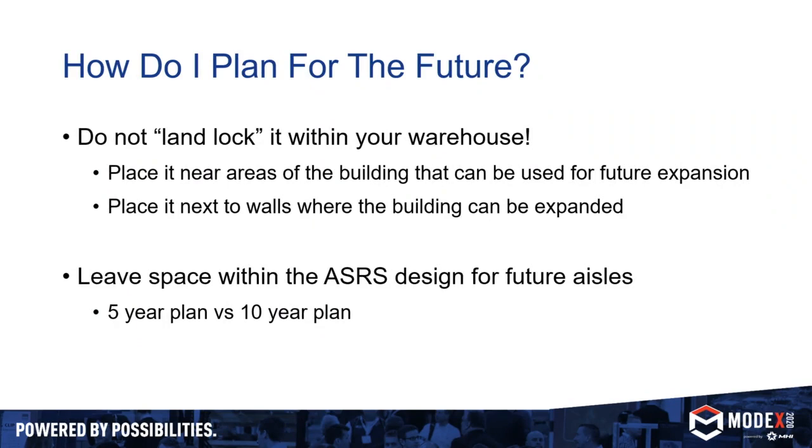And that goes into the next slide. How do I plan for the future? You don't want to put this ASRS somewhere where it's in a room, or off to the side, or somewhere that doesn't have any expandability built into it. You don't want to landlock it. You want to put it either in an area where you're able to build further in one way or the other, or against a wall where you have more land that you can possibly buy or develop to do an expansion later.